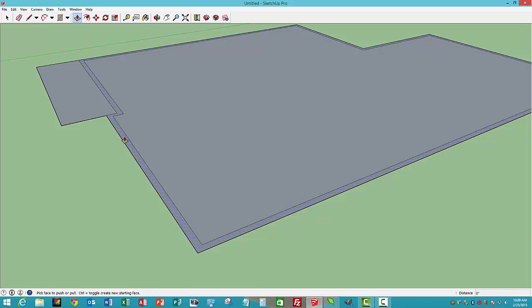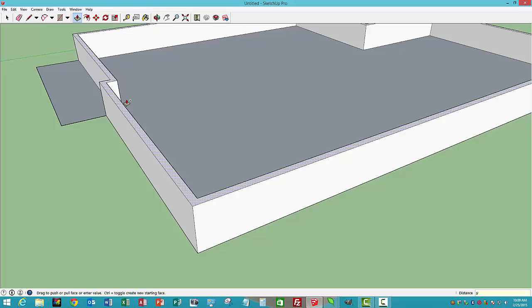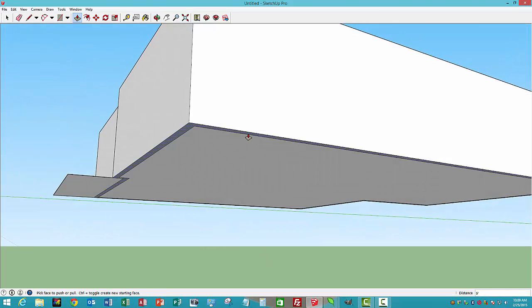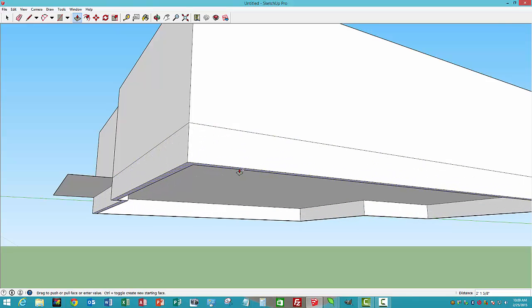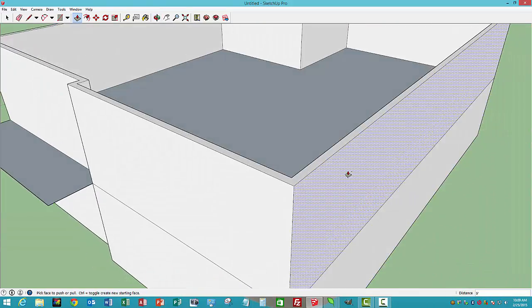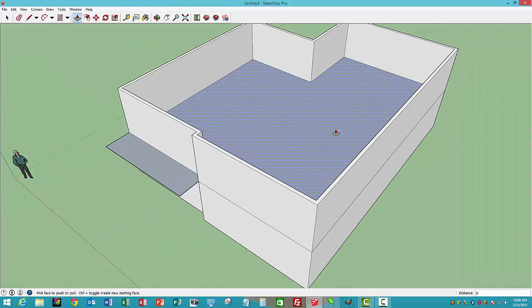So what I've done here was I offset inside that house a half a foot. I'm going to raise the shell, you would say, of the home 9 feet. I'm lowering now 8 foot to create like a basement, even if you have slab on grade, because the site's not going to be flat. You don't want these homes floating around.